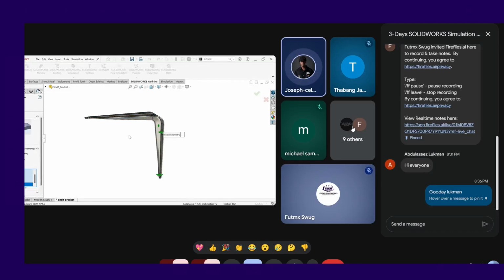If you run a simulation without it being fixed, especially in a SolidWorks assembly simulation where the connection between two parts may be wrong, it's going to move infinitely. It's going to give you an error saying it's sensing a very large deformation that's unrealistic.